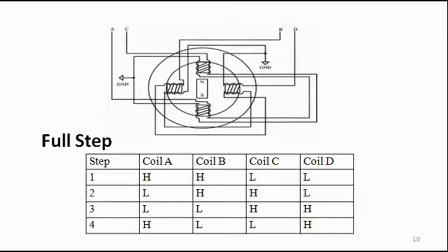Now, as I explained in the previous DC motor rotation program, we have to create a hex file. The target, that is external frequency, is 12 megahertz, and in output we should click on create hex file. Now I have not created any new project here. I am loading the same program into the same project.